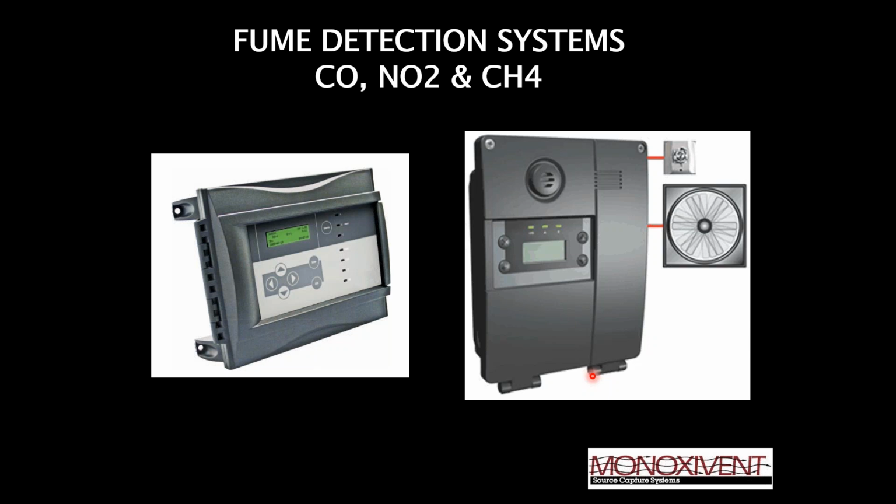So what we did is we partnered up with Honeywell. These are actually Honeywell systems, and we partnered up with them to add them to our product line because they just go so nicely together. These work where they monitor the air, and the sensors are set for certain thresholds, and when those thresholds are met, it can turn an evacuation fan on. It can open up louvers to bring fresh air in, all of that. So it was just a perfect kind of partner equipment with our source capture stuff. So that's it for vehicle exhaust.